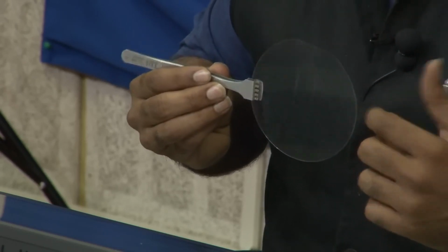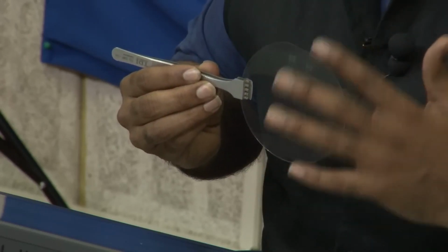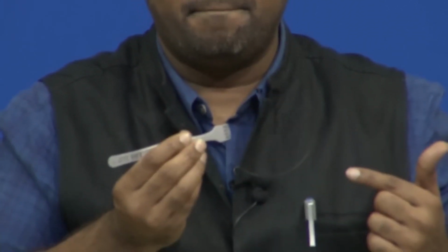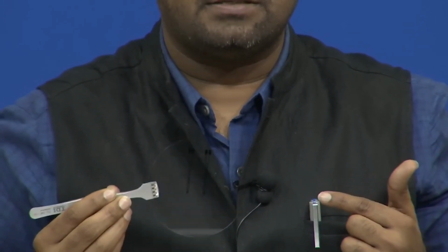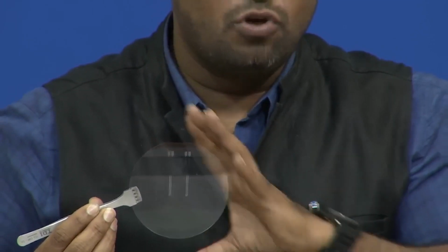Here there is no orientation because there is no crystal, everything is oxidized. SiO2 is SiO2, silicon dioxide, that is what glass is made up of. And you can see very clearly this glass in my hand. Now you see the glass wafer I am holding. Again, it has a primary flat, but it does not have a secondary flat. It need not have a secondary flat because there is no crystal orientation, there is no crystal here.